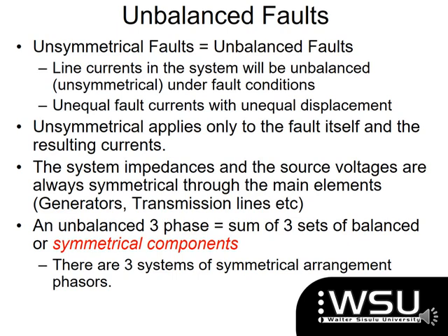The system impedances and voltage sources are always symmetrical through your main elements, which are your generators and your transmission lines. And an unbalanced three-phase system is equal to a sum of three sets of balanced or symmetrical components. That's where the word symmetrical components comes from.